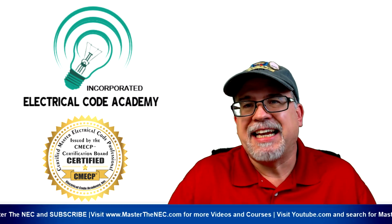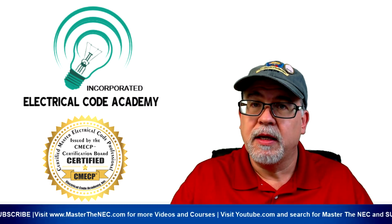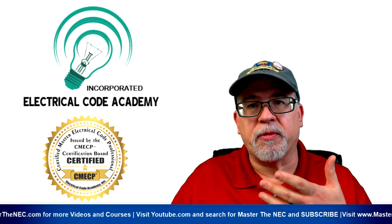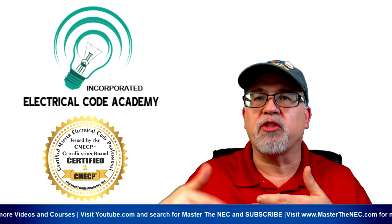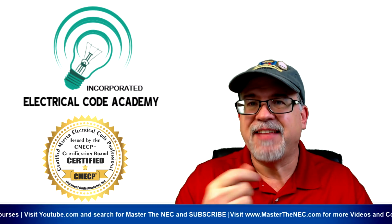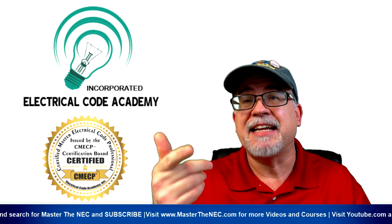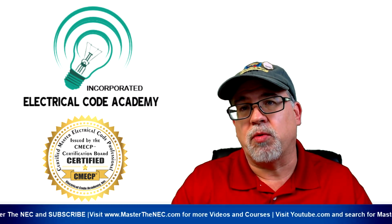Another question they might give you is they might tell you how many existing conductors are in a raceway, and now they want to know how many additional 14 conductors you can add. Well, you do the same thing. You take the 40% because you know you can't exceed the 40, subtract the value of the existing conductors, and whatever that value is remaining, you take that value divided by the 14 gauge conductor size that we saw in Chapter 9, Table 5, and that's going to tell you how many additional ones you can put in there.